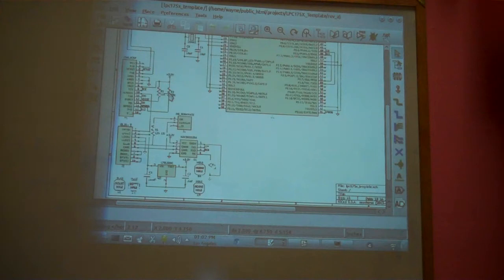And right there, that's a resistor. You'll see something here called a mounting hole. I always put my mounting holes on the schematic because they are in fact electrical; you can connect to your mounting holes. I don't as a rule, but they are an electrical device. In addition, they're usually the first thing you put on your board, because if you don't do that, you regret it.